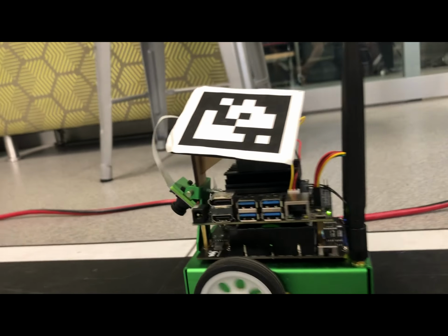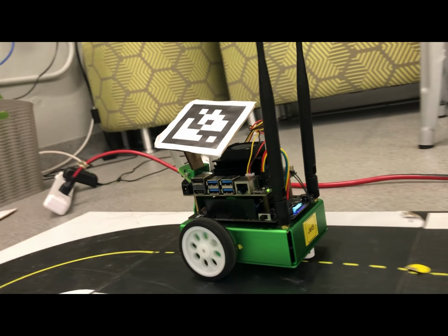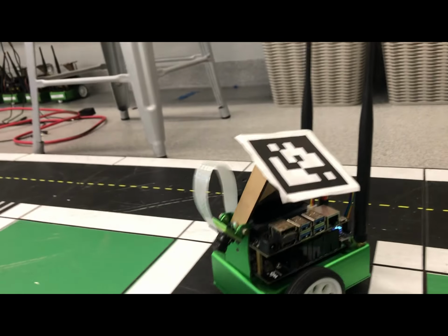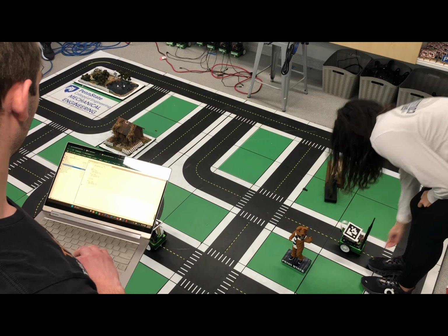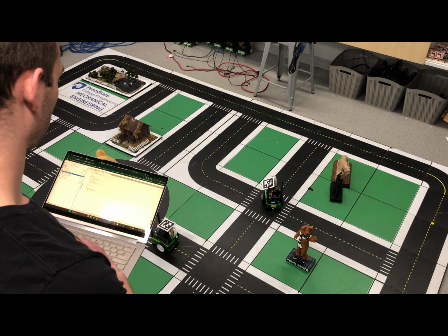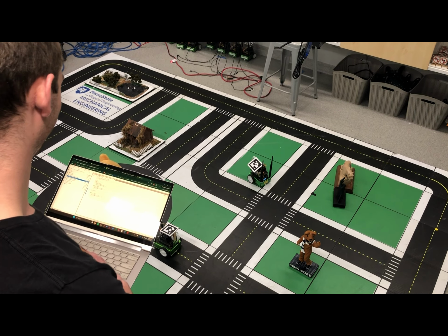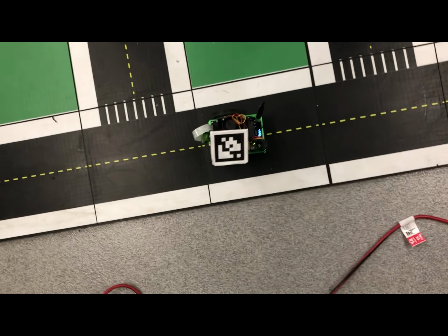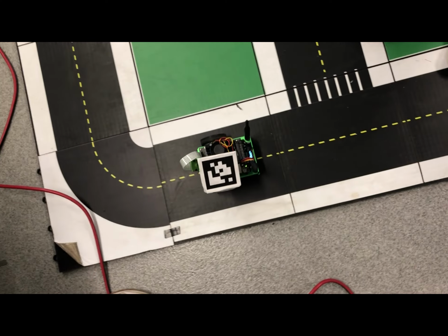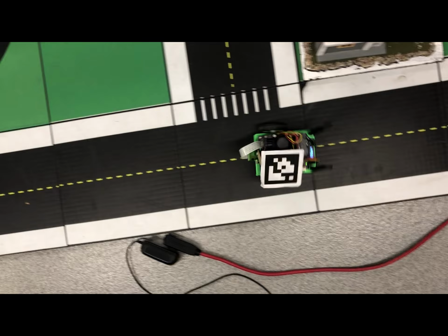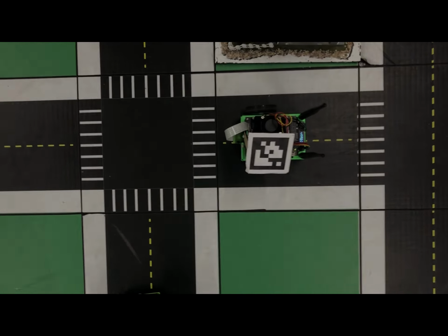With our binary map, we can input the current location and a target location to our code, and the code will produce nodes spaced across the road. Next, we can adjust the number of nodes, the distance between them, and the maximum number of node connections to find the shortest possible path to our target destination. Finally, our team developed an algorithm that allows the robot to make decisions at an intersection based off of the intended path. Because the robot uses line following, and there are no lines in the intersection, we need to implement a decision process to successfully navigate intersections.